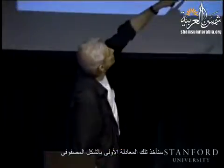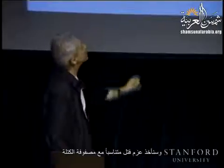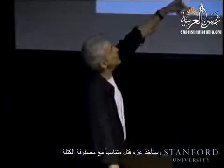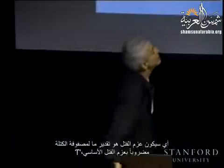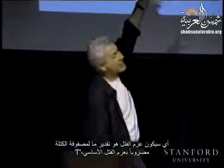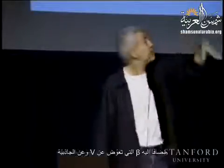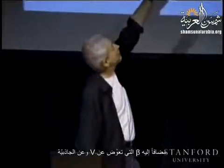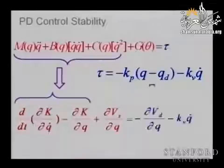Well, now we are going to extend it. And what we're going to do is go to that first equation in the matrix form, and we are going to take a torque that is proportional to the mass matrix. So our torque will be some estimate of the mass matrix times torque prime plus a beta that compensates for V and the gravity. And this is what we're going to do.